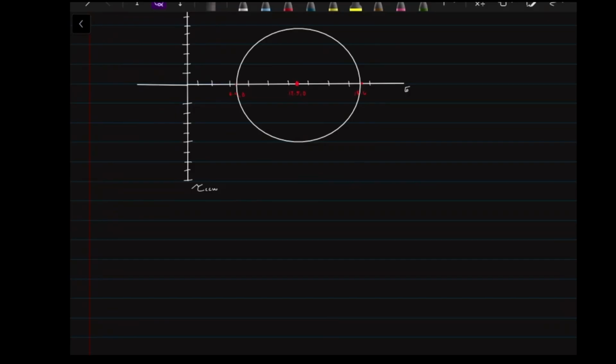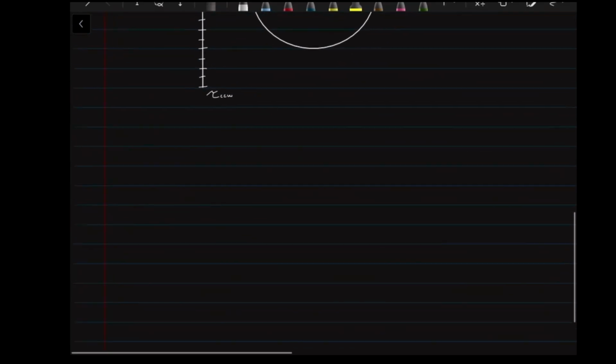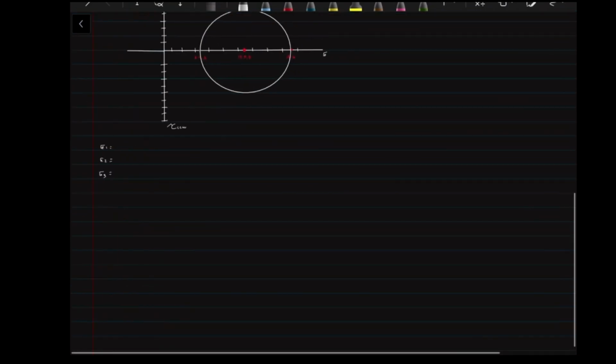We're doing great things. Now what we're gonna do is the principal stresses that it asked us. There are 3 of them, sigma 1, 2, and 3. That's very important. You should remember that. Principal stresses, there are 3 of them, sigma 1, sigma 2, and sigma 3. One of these is gonna be 0, and that is the furthest value to the left. So let me tell you, if we had a chart and our circle did this, this would be our sigma 3, this would be sigma 2, and this would be sigma 1. There's our 0 value.